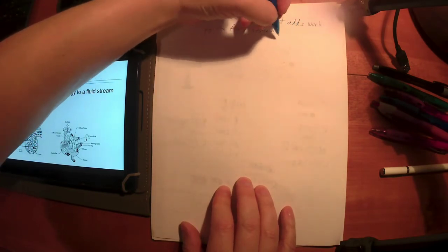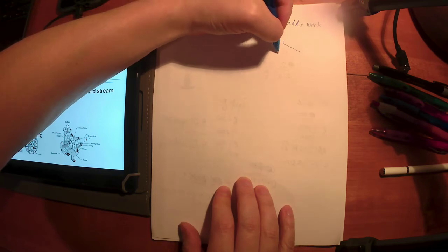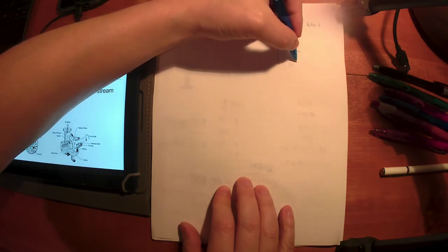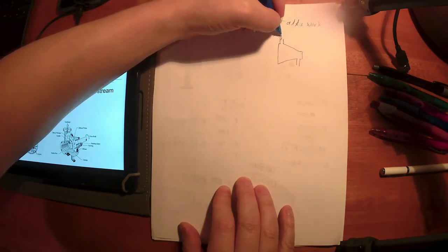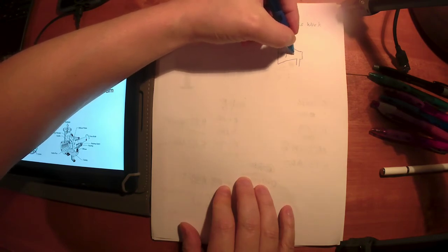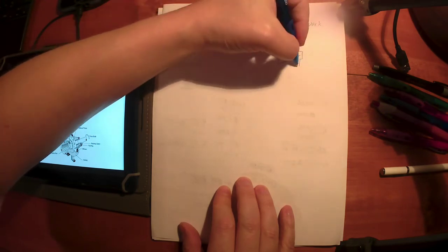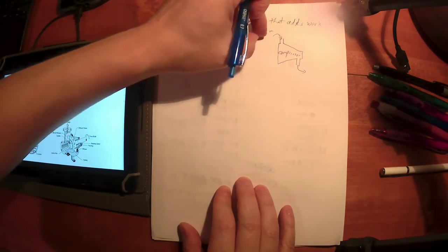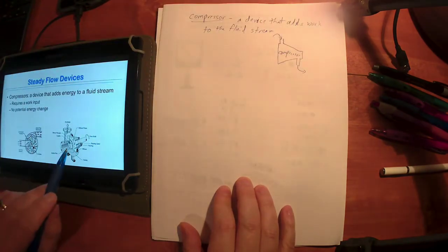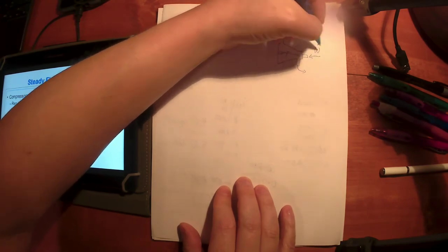That's kind of what we would call a turbo configuration of a compressor. This text likes to draw piston cylinder compressors. I don't really care for that. There's some technical reasons for that. Here's how I draw a compressor. I draw something that looks kind of like a nozzle, but instead of the fluid just moving through, I draw the fluid moving in the larger end of the barrel and getting squeezed down and moving out of the more narrow end. So as the fluid moves through, it gets squeezed down with some kind of a rotating shaft. We draw out here just a little bit of a rotating shaft and draw a power input.